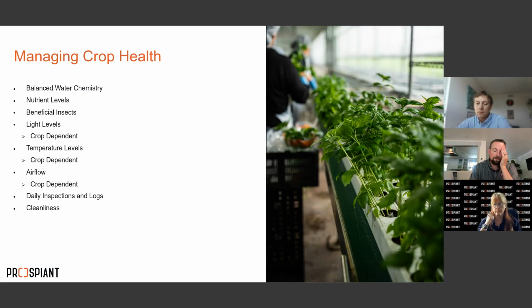And then the other thing is the fish, they don't want to be at a high pH, they don't want to be at a low pH like the hydroponic greenhouse does want to be. Hydroponic greenhouse might want to be at a pH of 6, and the fish might want to be at a pH of 8. And so if you're doing a strictly coupled system, you're really not optimized around either one of your two crops, your fish or your plants. Where if you do a decoupled system, you can dial in the exact water needs for the fish, the right temperature, the right pH, the right amount of dissolved oxygen, and you can do it in the right amount of nutrients, nitrogen and water, usually at a very low level. And then you could do the same thing for your greenhouse and still not have any real waste streams.